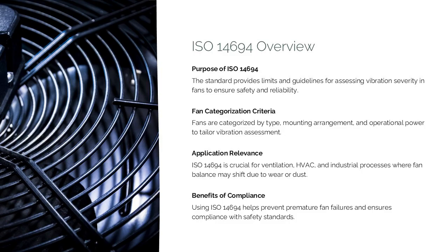Engineers use this standard to evaluate unbalance-related vibration, ensuring fans meet safety and reliability expectations. Since fans often accumulate dust or suffer from blade wear, ISO 14694 is especially relevant in ventilation, HVAC, and industrial process applications where dynamic balance conditions can shift over time. Using the standard ensures compliance while preventing premature component failures due to unbalance.